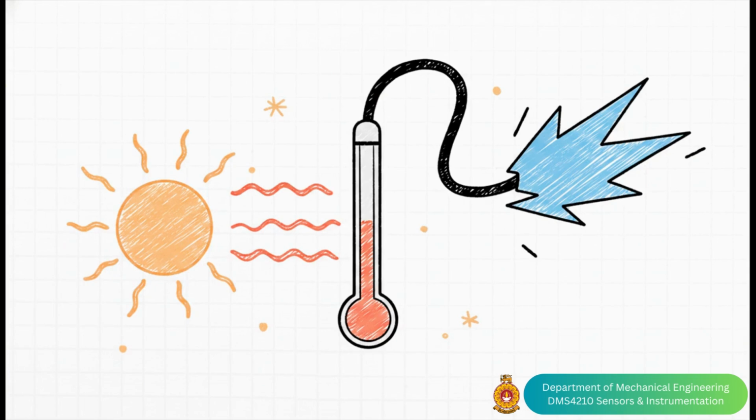This is where the physical quantity of interest, what we call the measurand, actually interacts with a sensing element. And thanks to a known physical law, this interaction produces a primary signal. Whether it's ambient temperature interacting with a thermocouple or fluid pressure hitting a super delicate membrane, this is the exact moment reality is captured. It's literally where the physical universe shakes hands with the electronic one.